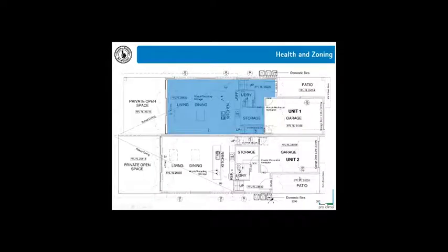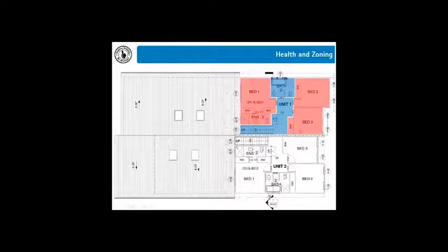So then I want to look at health and zoning, how we zone up the buildings, or what we assume in the NatHERS system, which is that we have day zones and night zones. But when you do this, you create humidity in the occupied zones, and in the colder zones, that's where all the moisture will be attracted to. The coldest walls in the house are where the moisture is going to be attracted to and create high humidity and then potential long-term mold growth.